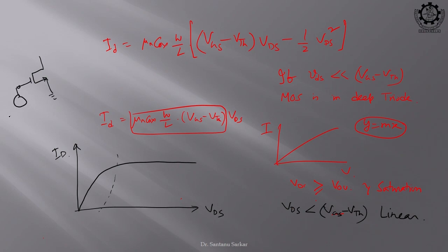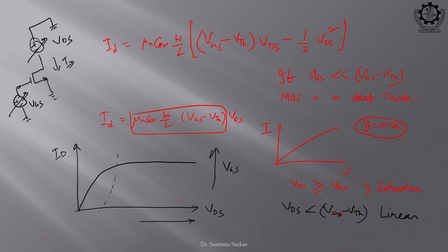Here you are applying one variable voltage, that is your VGS, and here you are applying another variable voltage, that is your VDS. So, you are getting a variable current ID. So, what is the meaning? How many variables are there? One variable is VDS, another variable is VGS. So, if you have different VGS, you will get a different set of equations for ID, right. So, this is known as the graphical plot. From this graphical plot also you can calculate the same thing.